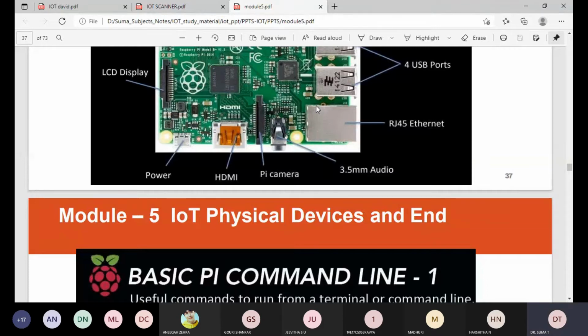However, any excessive use of USB ports or even heavy loading can cause the voltage to drop and cause instability during use. The latest versions of the Raspberry Pi B+ and A+ have a low voltage indicator icon to notify the user if there is a problem with the power.